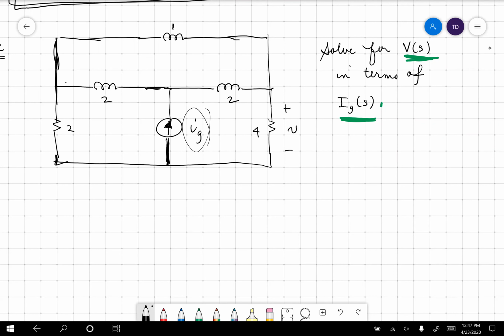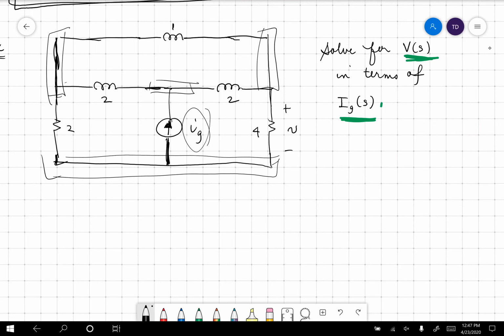Good. How come 2? Is it a current source? Good. There's a current source. So there's 2 mesh equations. How many nodes? Well, let's check the nodes. Four nodes. I don't see any supernodes. One of them will be referenced. So we can write 3 nodal equations or 1 mesh equation.